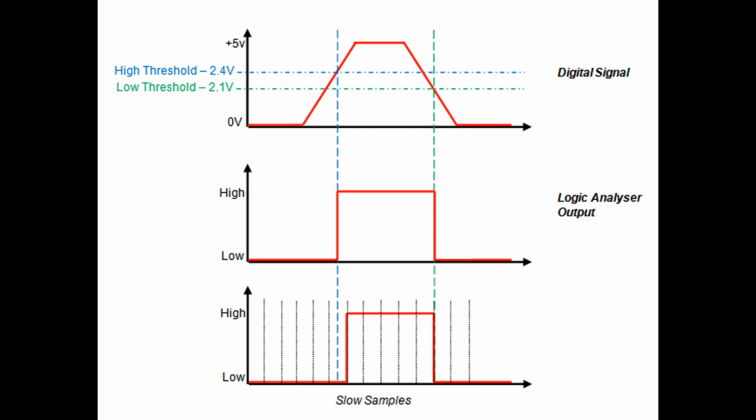We are mindful that the sample speed is important if you want accurate timings. We are only analysing slow clock speeds with cheap analyzers. We cannot view high-speed signals due to the lack of sample speed and probing issues. When you start probing at hundreds of megahertz, the probes themselves will affect the signal through their inductance and capacitance, causing inaccurate results. To probe at these speeds often requires expensive test equipment and extensive knowledge of the field.